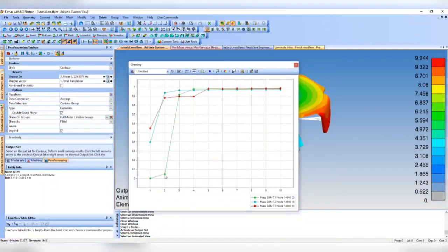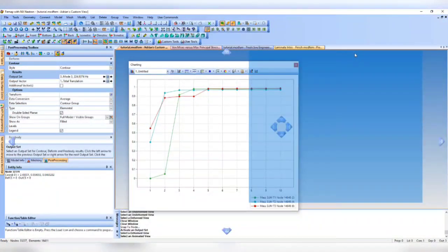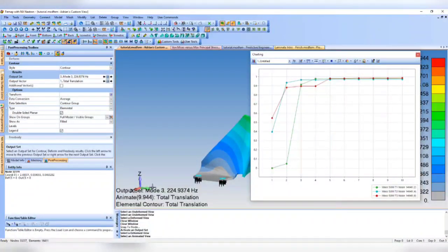And these are all in different directions. This green is Y, meaning the modal mass participation in the Y direction. The modal mass participation in the X direction is X, and this purple is Z. That's why we have 3 separate graphs for each direction. The main intent of this is just to show that normal mode 1 is capturing about 40% of the total mass participation and around 55% of the overall system for T2 and T3.